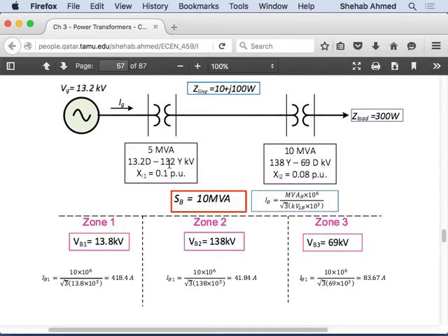For this specific purpose, for the specific objective of selecting equipment rating, does phase shift matter? If I just want to select a cable for this transmission line, I don't care what the phase shifts of the voltages are. I just care about the ratings, right? So typically, I will tell you to ignore phase shifts when we solve problems. But we will solve problems without ignoring phase shifts, so you see what the effect is. But when you're talking about equipment rating, I don't care.